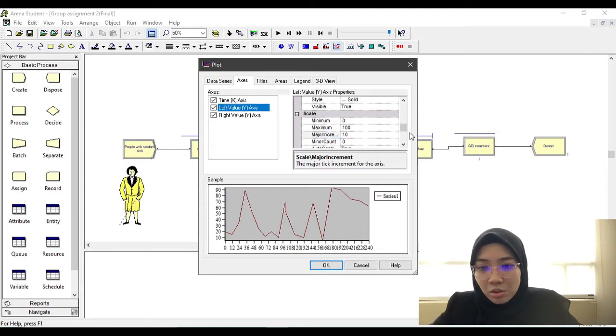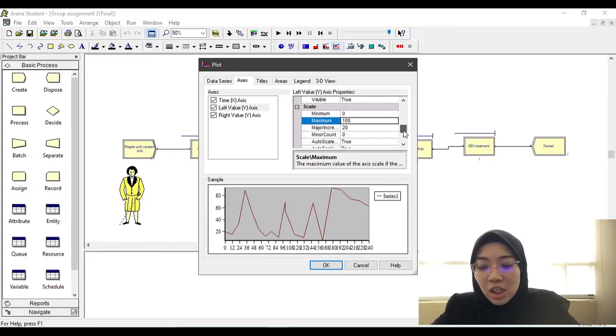And then go to the left value. For the left value, go through with the measure increment. Specify the value of 20 for the scale measure increment property, so that the measure tick marks on the y-axis are displayed every 20 units. When setting the axis values, leave the default value for any property not specifically mentioned here.